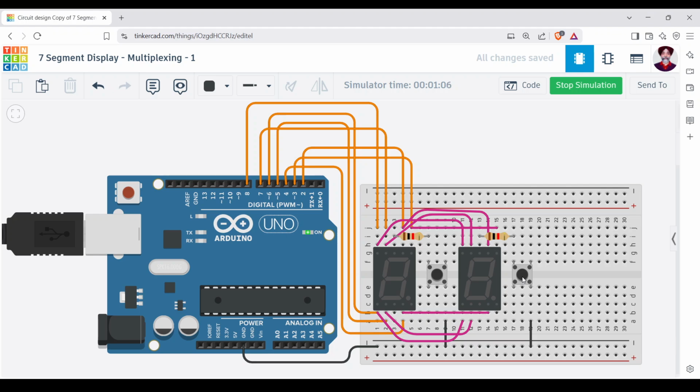The displays are displaying the 4 and the 5 so fast that our eyes don't see that one is switched off and another is switched on, and again that is switched off, again 4 comes on, and so on. Our eyes don't come to know. Okay, so what is actually happening? One gets switched on, displays, switched off, again second one is displayed.